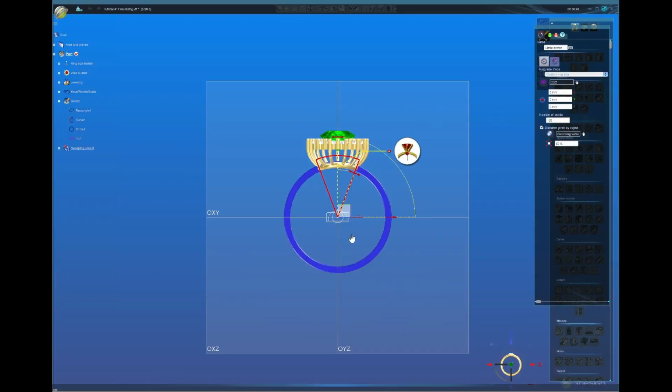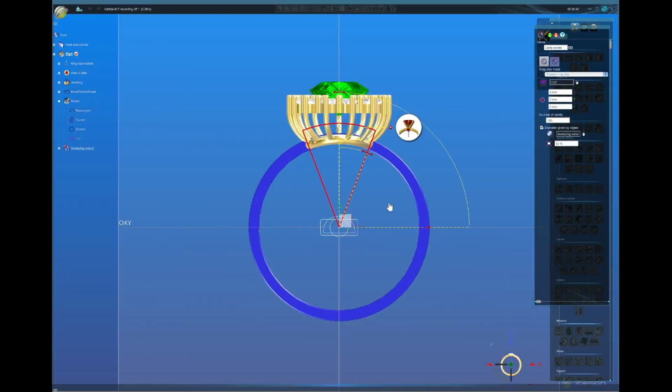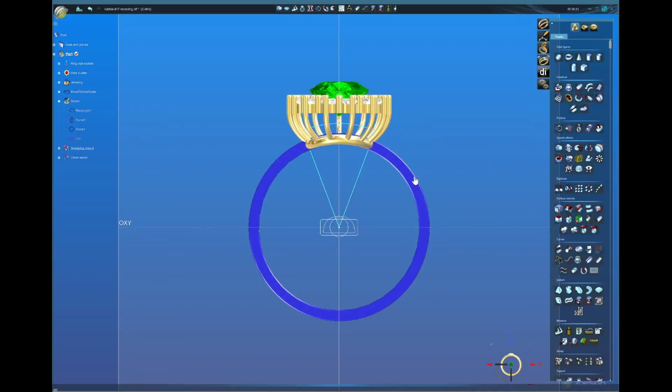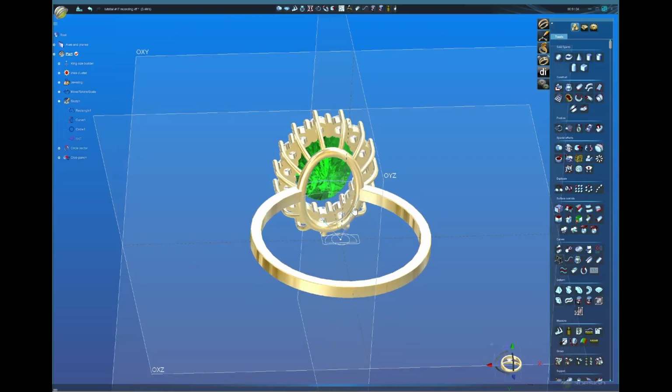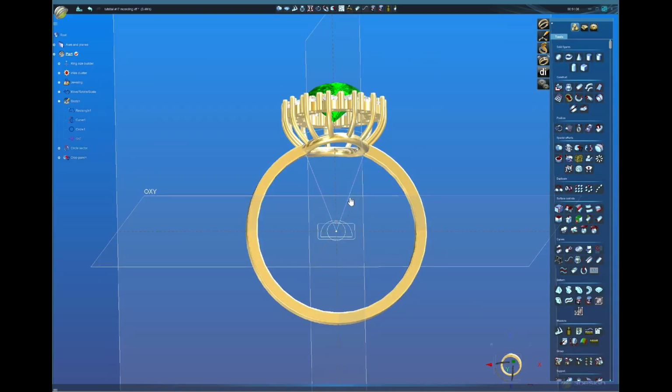You could do the same thing with the plane, but the software gives us this tool to be faster. So you click there, click OK. I have my shank highlighted. I click Control down, click on the curve, and come over here, and it cleans the inside part for us. Okay, we don't need that anymore, this curve.